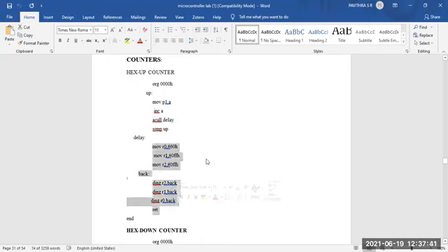That is for counter. Okay, delay program: MOV R0, #60H. Okay, R0 value is loaded with the 60. Why it is 60 means, 60H is nothing but this is for the TMOD register. Okay, R0 we are using as a TMOD register. That is nothing but counter 0 in the mode 2. Okay, and R1 is loaded with 0FFH. That is nothing but FF is the maximum value we are counting. And then till it becomes 0, it will keep on counting. I'll show how exactly it will count.